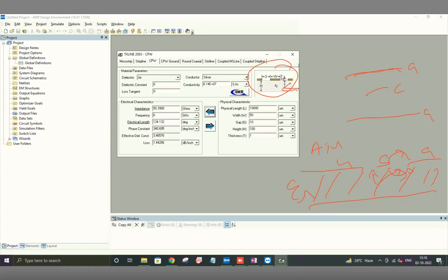But if you look on the back side of that, you see that it has a metal. So there is a variation of CPW, which is called CPW ground. The only difference here is that now there is a metal plate at the back as well. So this changes the capacitance per unit length and inductance per unit length, because now the capacitance is between both the side ground planes and the bottom ground planes as well.